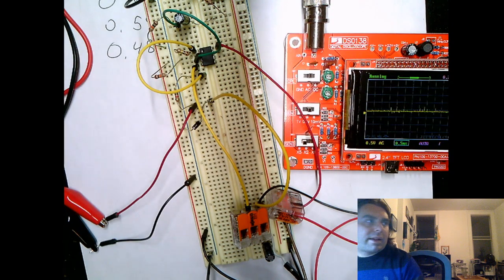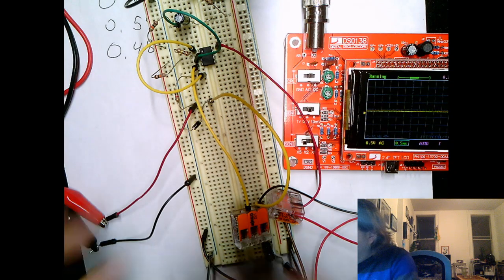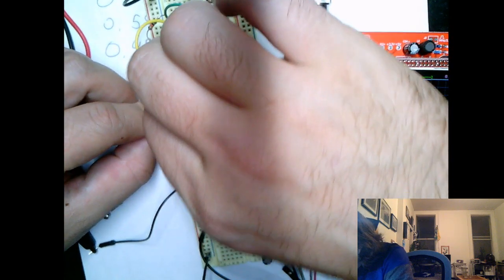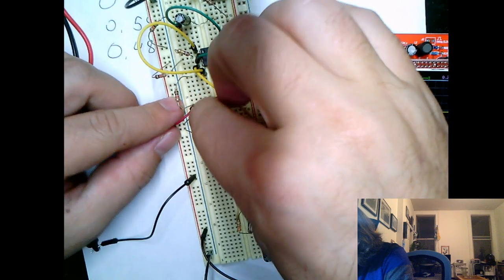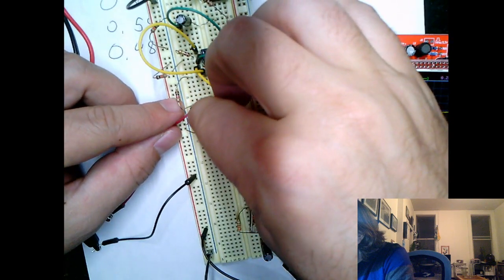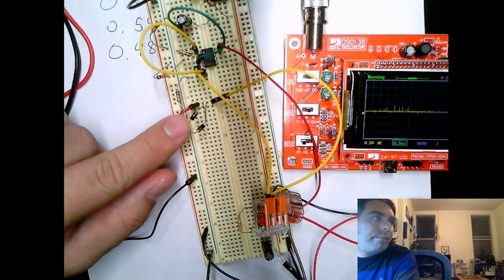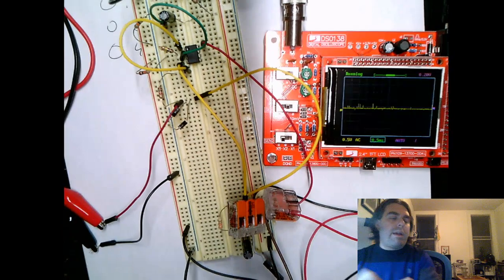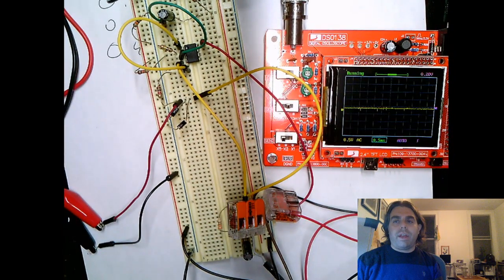So I'm just going to take a second diode, and I'm going to connect it into the same rows as my first diode, but backwards. So the cathode, the negative part, is actually now facing my signal path, right? So let me do a quick test with a sine wave first. Let's see what this looks like.